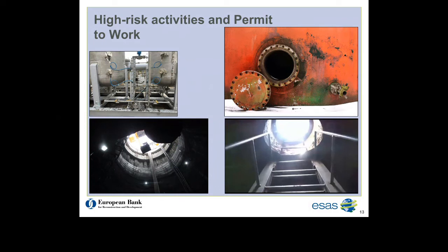A key risk identified during the visit was the control of risks associated with work in confined spaces. Our observations included the fact that ventilation is poor, and where mechanical ventilation is provided to the confined space, the ducting is often damaged and leaking, with no evidence of inspection and maintenance. Gas test and analysis is not always undertaken before entering a confined space. And there is no control over who can access a confined space or system to record who is currently working within that confined space. Furthermore, breathing apparatus is not available.